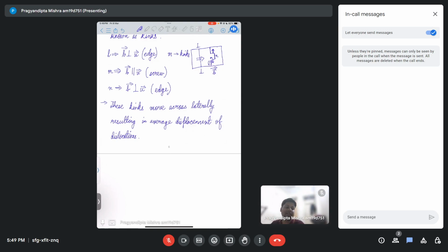When a dislocation is getting formed, ideally it is trying to minimize the energy. Now if these sharp corners are getting formed again and again, then the energy will not get minimized very easily. So in order to ensure that the energy gets reduced, the dislocation will eliminate the sharp corners by rounding them off to some extent.